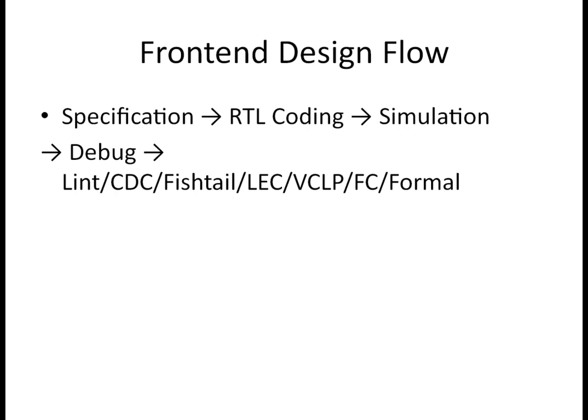Multi-cycle part is where it is expected that data is traveling from source to destination in more than one clock cycle. So in that case, we will be telling the tool, okay, this is the path where data will take at least more than one clock cycle to travel to the destination.